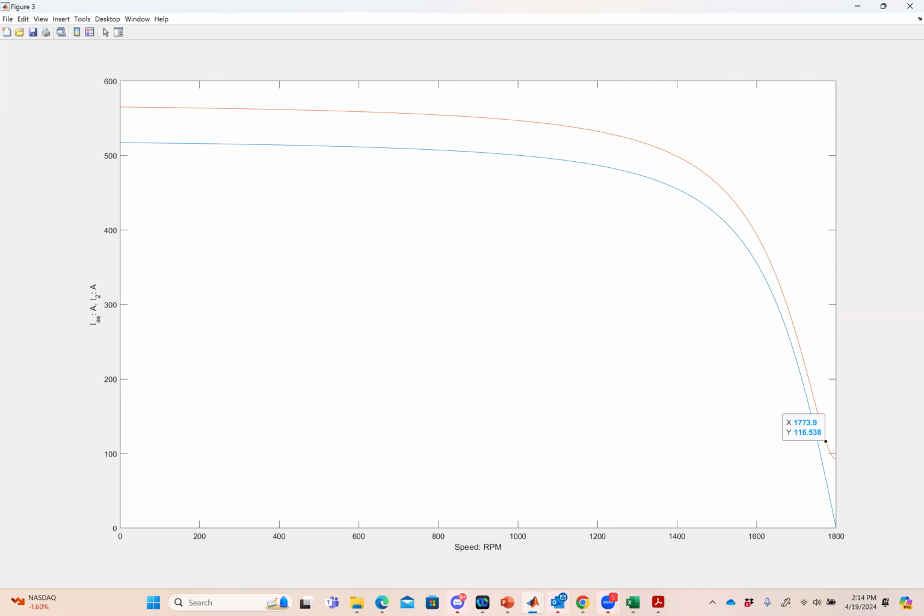But I might want to vary the speed of the motor. Let's say I wanted to go at 500 RPM. That would be an absolutely terrible idea with this machine. It'd be a lot of current. What could I do instead if I wanted this machine to go at a lower speed? How could I make the machine go at a lower speed more safely, perhaps? Well, I'd lower the voltage. And more importantly, along with it, I would also change what about the voltage?